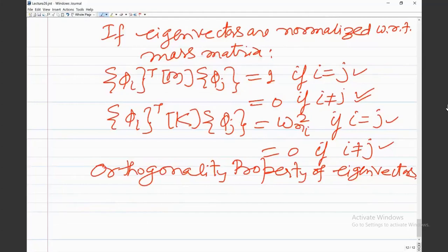And whenever there are curved boundaries, then you actually need curved boundaries of the element in the physical coordinate space. So you will go for the 8 noded isoparametric element.